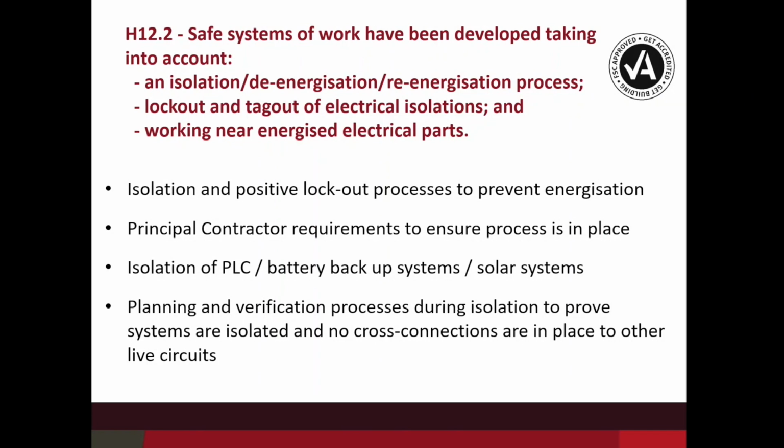What we look for is, how do we plan for understanding the systems that are in play at the site, what the isolation and de-energization requirements are going to be, how we're going to prevent them from being re-energized, and making sure that we have no cross connection or even illegal connections which might be providing a power feed into the areas that we're about to work in or on.